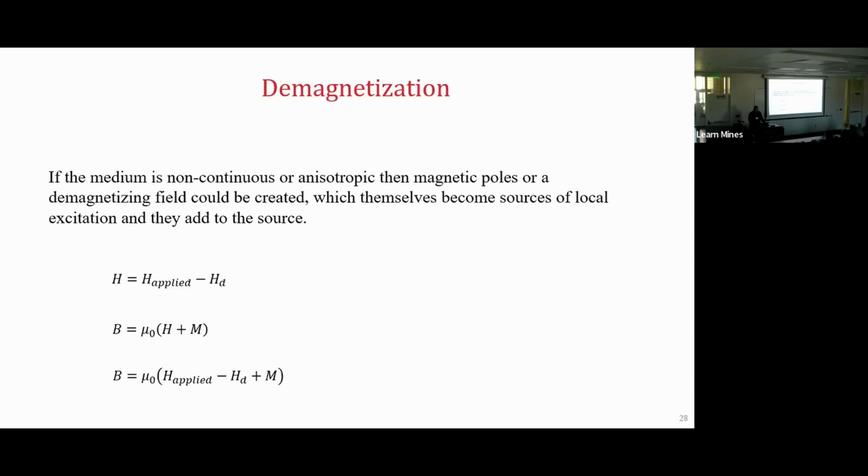We covered all this basic content. Now let's go a little deeper into the demagnetization factor H_d. We just said that if you have a demagnetization factor due to the undesired distribution of the magnetic dipoles, and you generate H_d, the overall effective field applied to your material is the one you applied minus the one generated by the magnetic dipoles, the demagnetization field.